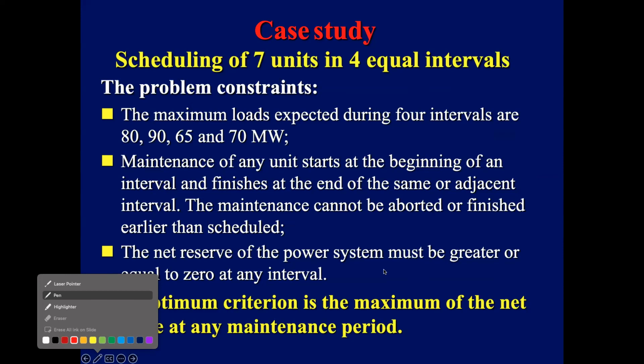So you're going to maintain generators, but since these generators serve clients, you want to establish a schedule of maintaining some of the generators while the others are still working, so that the clients don't lose out on power, because there are some critical clients like hospitals where power is needed all the time. So you need a maintenance schedule such that while you're maintaining the generators, you continue serving power to the clients.